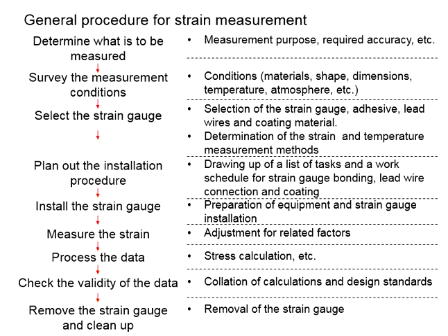Dynamic gauge can also be used. Or if you are measuring the crack width, there are also ways to measure the crack width of concrete. The bottom line here is you need to know what you are measuring, why you need to measure that, and decide whether strain gauge is suitable before you proceed with the following steps.